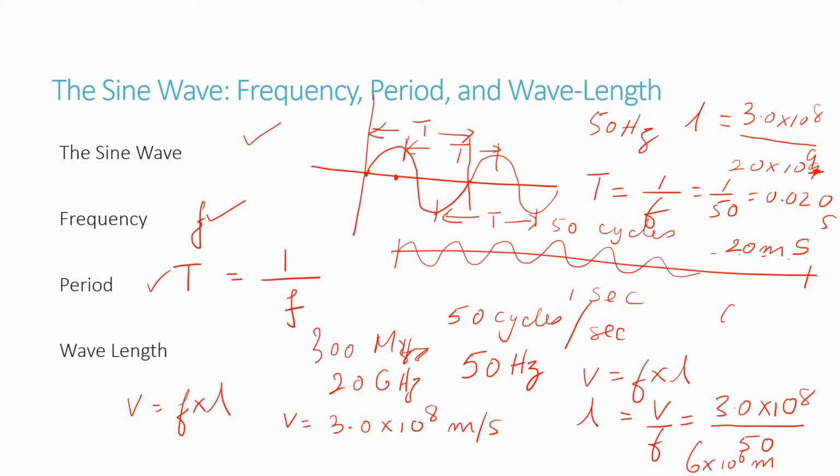That works out at 0.015 meters, right? Which is really 1.5 centimeters. So very short. So that's why, for instance, you have a cell phone. There's actually an antenna inside that cell phone, which is very, very short, right? So when you're dealing with very high frequencies, the wavelength is very short. But for our purposes, we don't have to worry about wavelength when we're dealing with lower frequencies like 50, 60 hertz, or even 400 hertz.